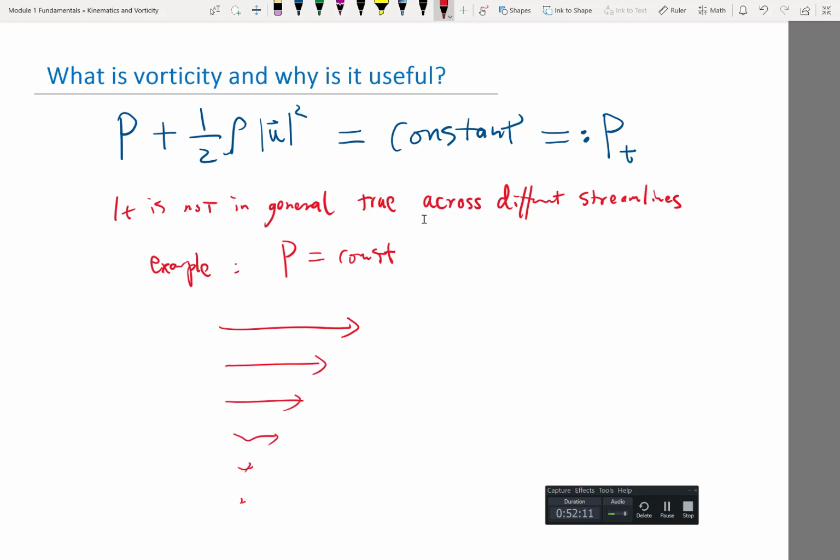Ignore viscosity. Just think about the flow fed in with a higher velocity on the top and lower velocity at the bottom. Because there are no viscous forces and no pressure forces, the flow just goes its own way, cruises with no acceleration, no deceleration, no turning at all. Is stagnation pressure constant across the streamlines?